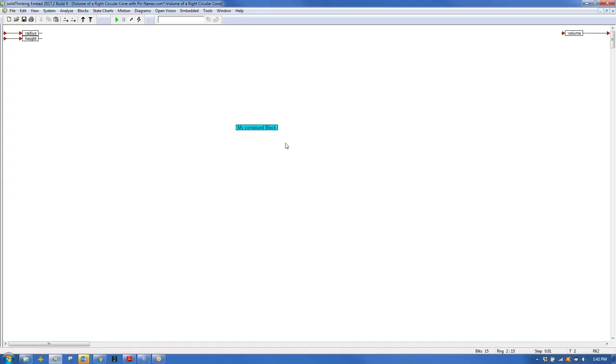Now, it didn't create any pins on it, so we can add those pins to it. If I go up here to the menu, you see right up here at the top these two selections, the plus and minus. I just click on the plus, bring this down and click on the left side. I'll add some pins to it. And I'll do the same thing on the right side. I'll add a pin to it. I can add a few pins to it. If I don't like them, I can remove them with the subtract arrow. Now, all that did was add pins. It didn't do anything internally. If I go inside, you see the pins are here, but they're not connected to anything.